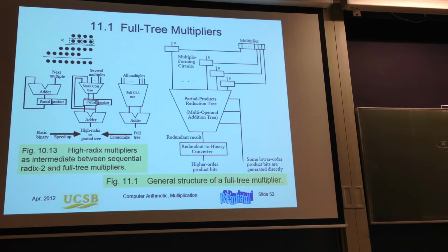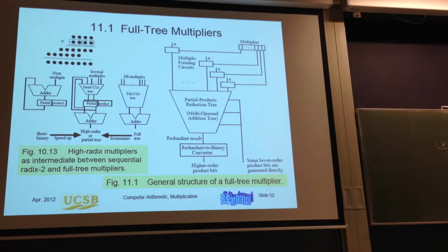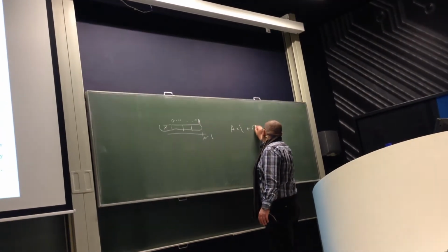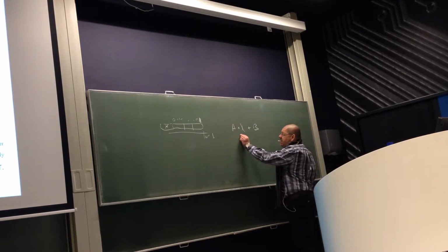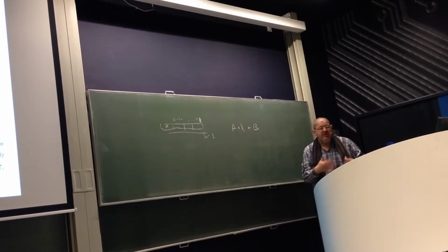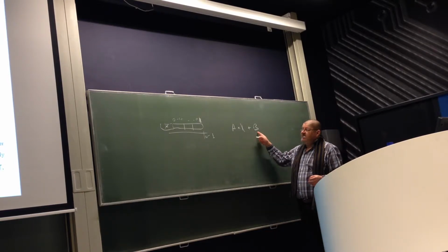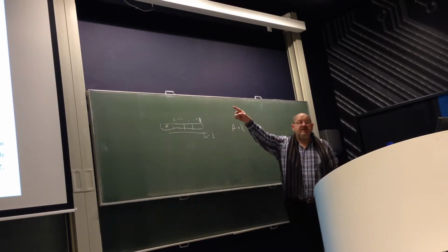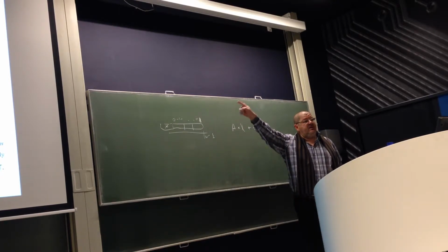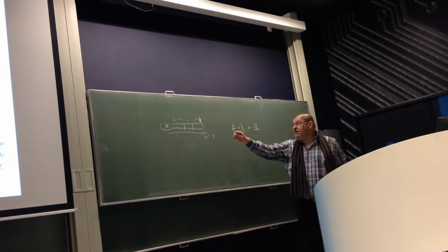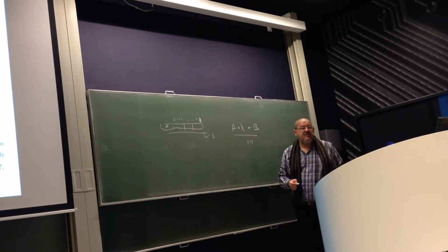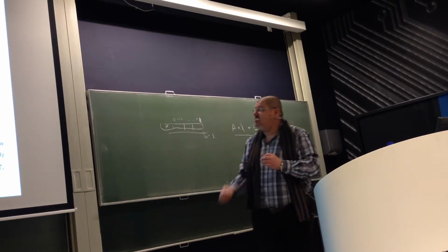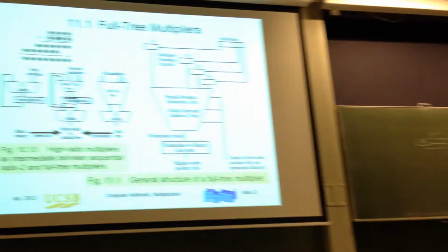It's very often that you have to compute this. Now, if I do it without support, this takes 2 cycles and this takes 1 cycle, and this will end up in 3 cycles in a processor. Because this B can be seen like another line in my partial products, I can get this in 2 cycles. And this is typical in DSP processors.